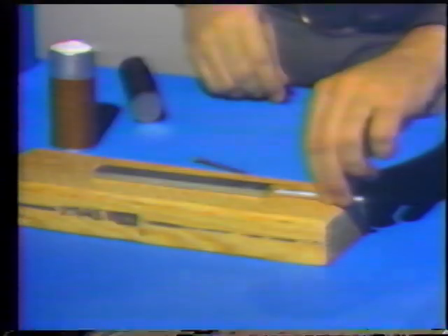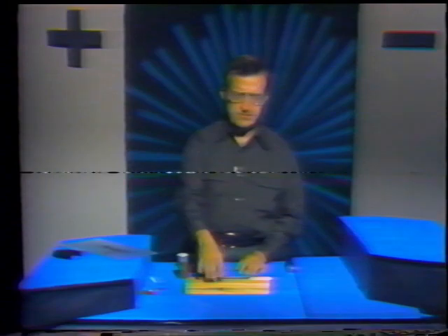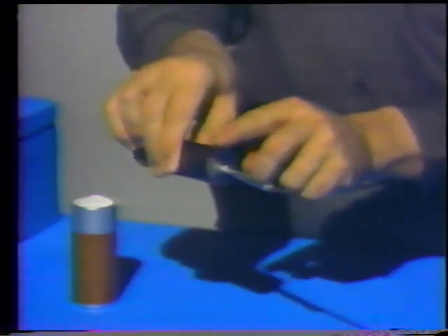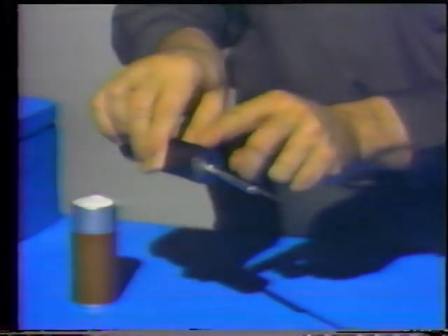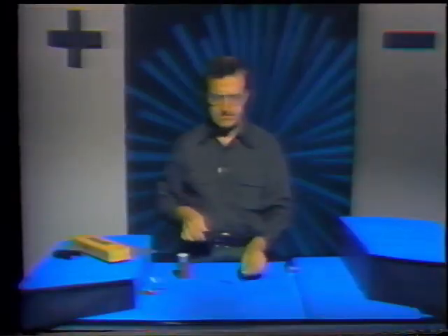We can even increase the size of a force field by placing a piece of steel next to the magnet. Steel and certain other metals can add to the power of a magnet by becoming temporary magnets themselves. Now you can see what I mean right here. This magnet can't pick up this nail because they're too far apart. Now, look what happens when I put this steel bar between the magnet and the nail. The nail is picked up. And as long as this steel bar is in contact with the magnet, the steel is magnetized and it attracts the nail. When I remove the magnet, the nail drops off of the steel bar.